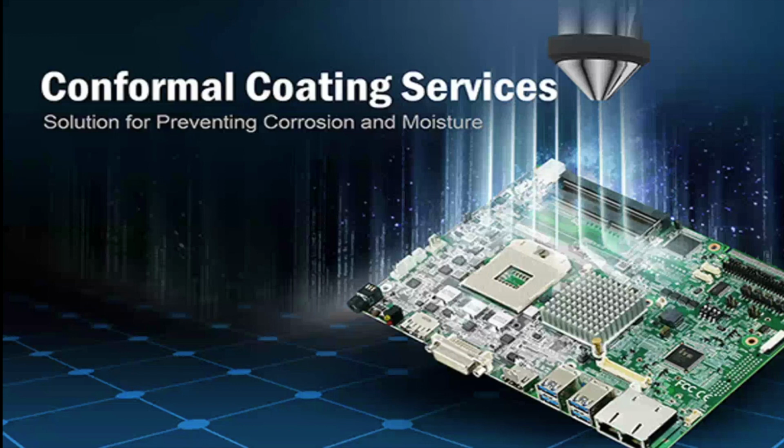Conformal coating is something where there's additional cost because it's an add-on process where you spray a coat on the board to protect it from moisture, rusting, or dirt and dust issues that may cause conductivity. When you do conformal coating, you can't coat the entire board. Certain areas are not allowed to be coated. This is quite standard, just to take note of.